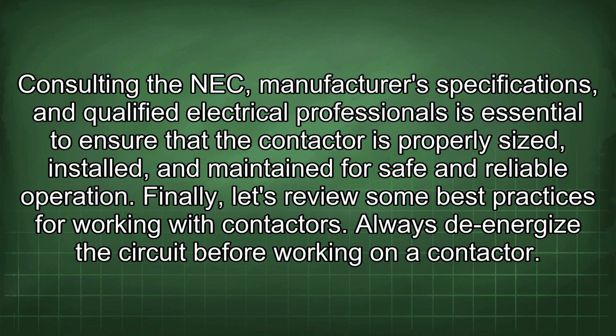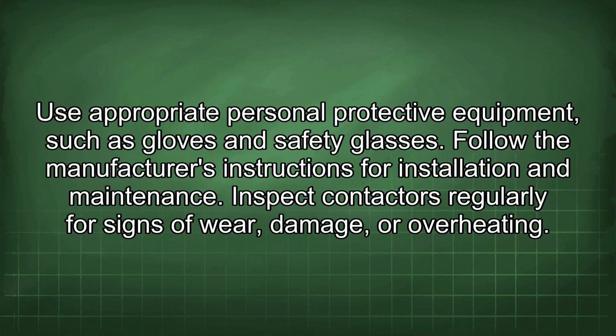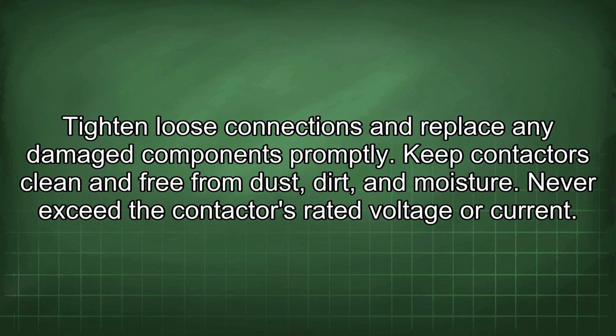Always de-energize the circuit before working on a contactor. Use appropriate personal protective equipment such as gloves and safety glasses. Follow the manufacturer's instructions for installation and maintenance. Inspect contactors regularly for signs of wear, damage, or overheating. Tighten loose connections and replace any damaged components promptly. Keep contactors clean and free from dust, dirt, and moisture.